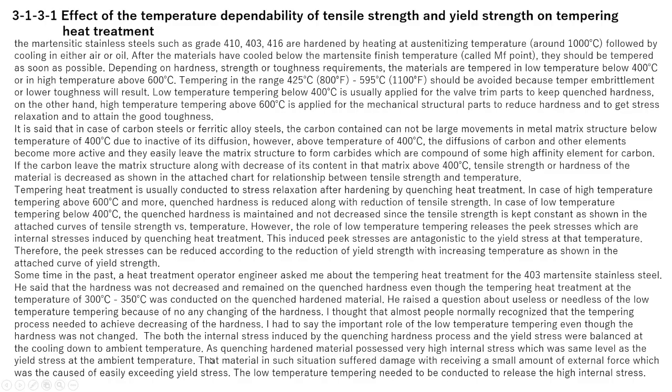As the quench hardened material possessed very high internal stress, at the same level as the yield strength at ambient temperature, material in such a situation suffered damage on receiving a small amount of external force, which easily exceeded the yield stress. Low temperature tempering needed to be conducted to reduce the high internal stress.